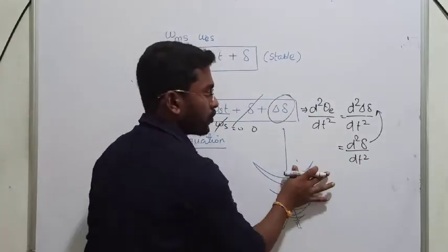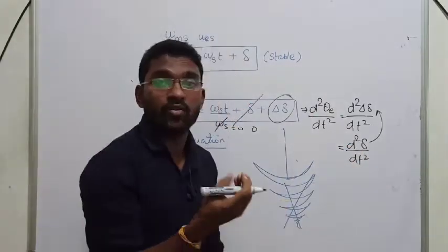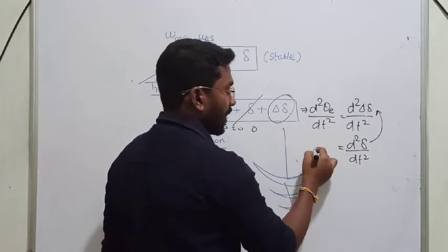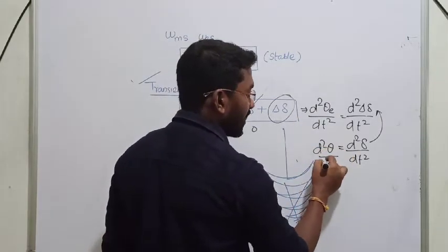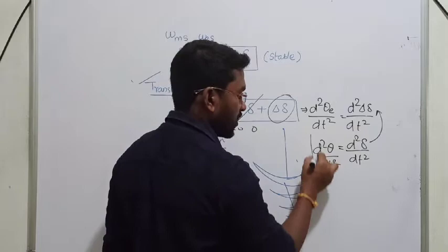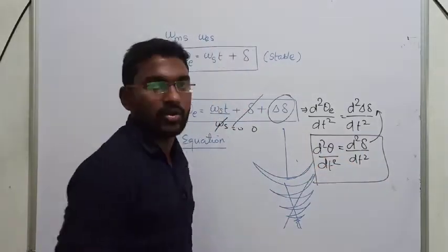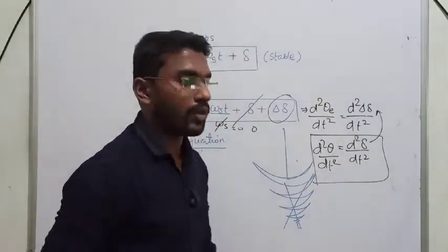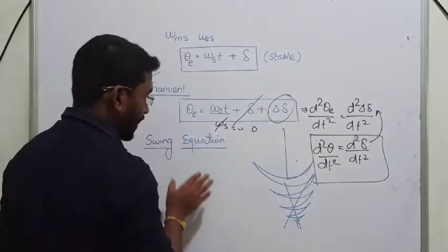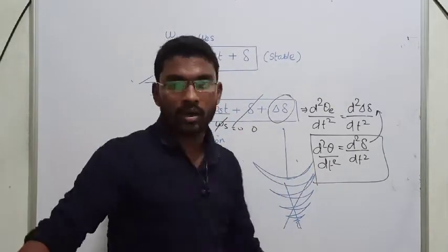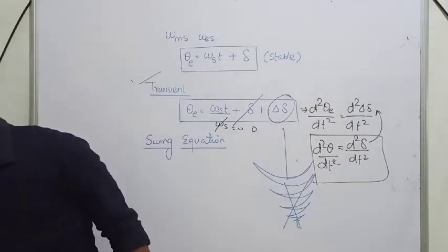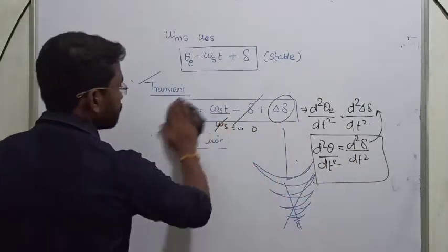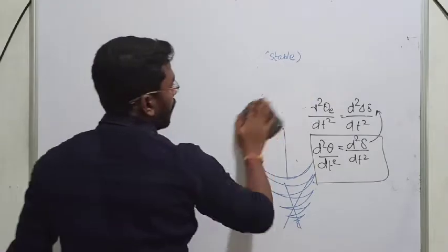What I have understood here is that the changes in the value of delta will be represented in terms of electrical degrees. That is called acceleration or deceleration. We know this is the acceleration equation, and we know the formula for the acceleration. Now let us develop the electrical equivalent equation for this swing. Just remember this equation now; from this I am slowly developing the equation.